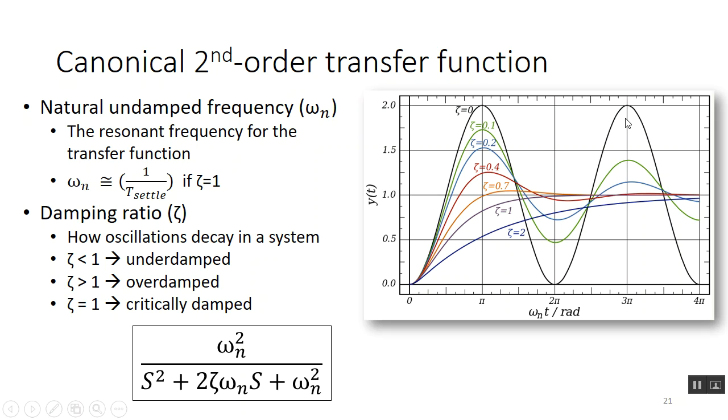Okay. It also allows you to add some dynamics really easily and say, maybe it's underdamped. Maybe in this conversion, you want zeta to be a little less than 1, like 0.7 or 0.4, so that the transfer characteristics have a little oscillation. That might be what you want to capture, and that's a super easy way to do it. So what I did, and it's really easy, you just drag and drop the transfer function, put a mask over it, and convert. You could use both the damping ratio and the natural frequency together, or just use one. I just used the natural frequency and said it's going to be critically damped.